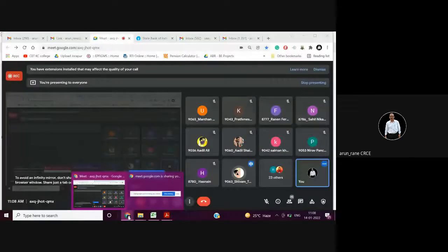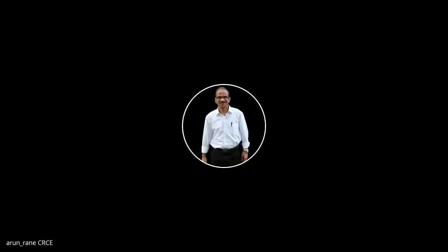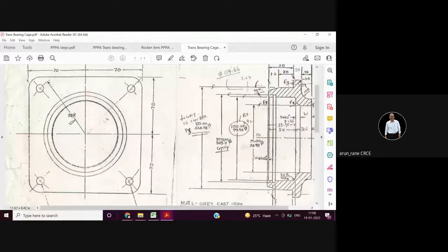Yeah. What I'm asking is, this quantity is say 500 pieces. See, the yearly requirement is say 72,000 pieces, or say 60,000 pieces. That is the yearly required quantity. 60,000. Yeah. So per month, you are not going to manufacture all the 60,000 pieces at a time, because there will be a lot of inventory. So you will take a batch of say 500 pieces in a month, and you will complete a target of 60,000 pieces. Now your batch size is 500.